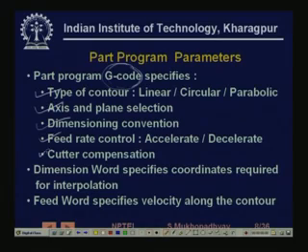Then there is something called cutter compensation, because you need to ensure that the dimension is actually created on the surface of the part, but not at the center of the tool which is cutting. So there is some cutter compensation which has to be done, which we are not dealing with.